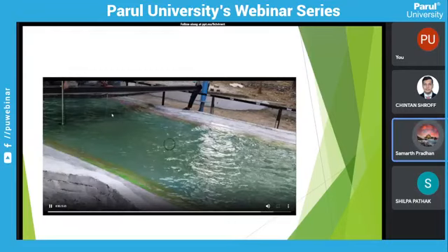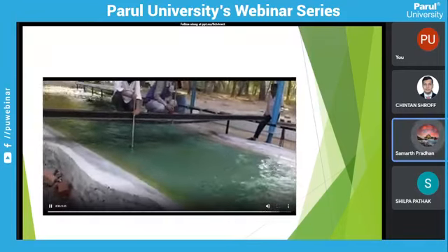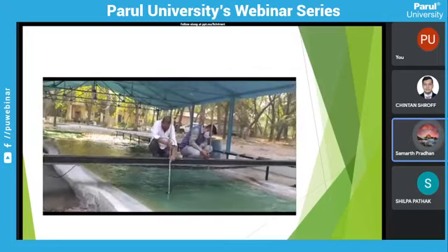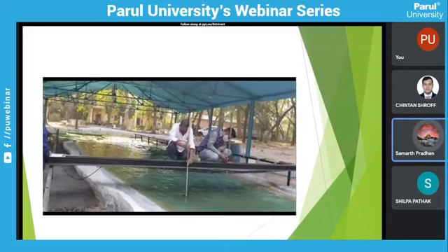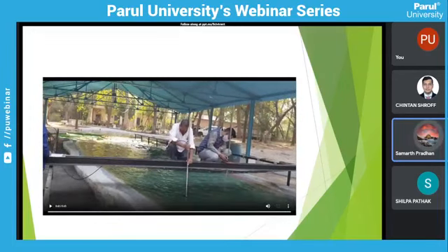So this is the model of the riverfront. Presently, we are working on, as I already mentioned, the city of Gandhinagar, between Shahpur Bridge and PDPU Bridge. That is a 4.5 kilometer riverfront. That is a mobile bed model, and this is a rigid bed model, because Sabarmati has sandy strata. In a rigid bed model, you cannot get scour.